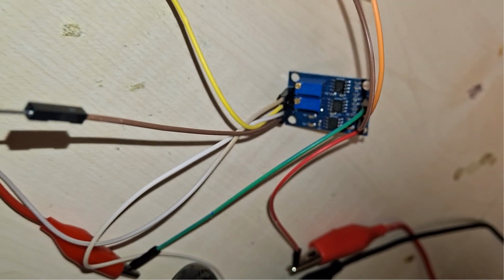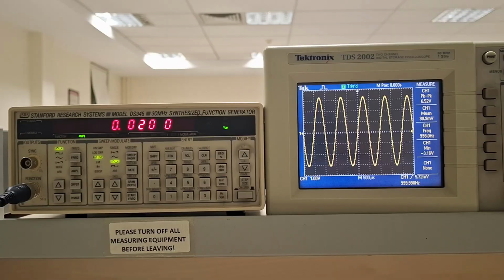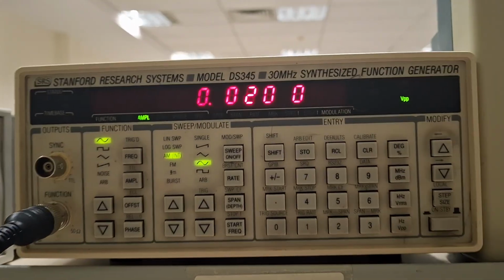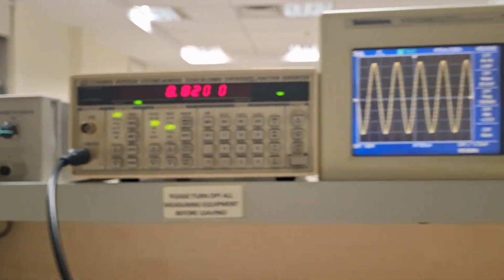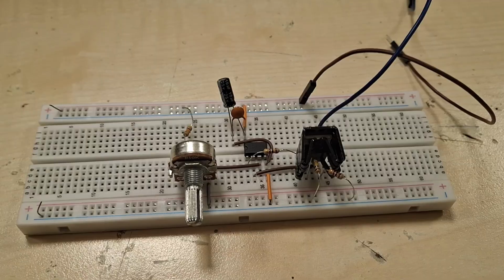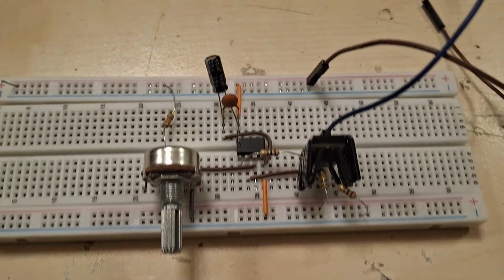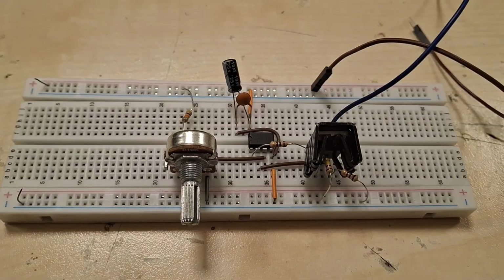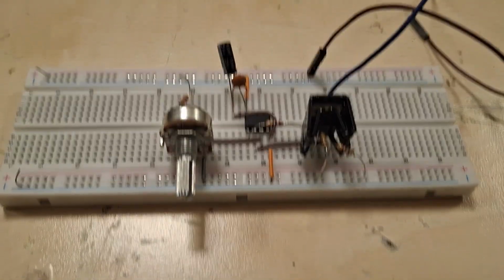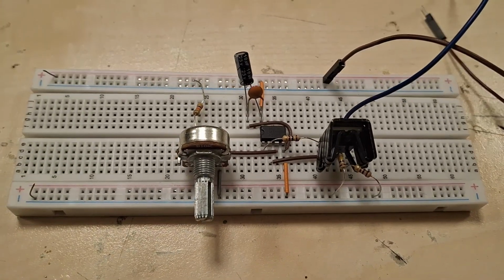The AD620 allows us to boost extremely weak thermoelectric signals, especially at the microvolt level, to readable levels by minimizing common mode electrical noise. The constant current circuit we built minimizes data collection errors by providing a completely stable current to the samples, unaffected by temperature changes.